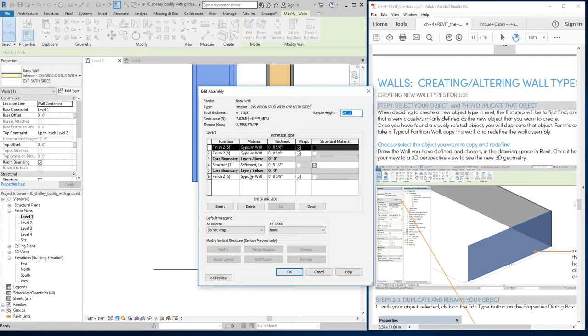And then the other tricky thing just in general for everyone is getting the layers of that assembly in the correct order, right? Because if something is not in the correct order, you'll get an error. This is wrong, row 6 error, and it's just a pain in the neck. You just want to scream sometimes, right? So just make sure they're ascending up towards the exterior 1, 2, 3, 4, 5, and then 1, 2, 3, 4, 5 down, right? And it should be good.